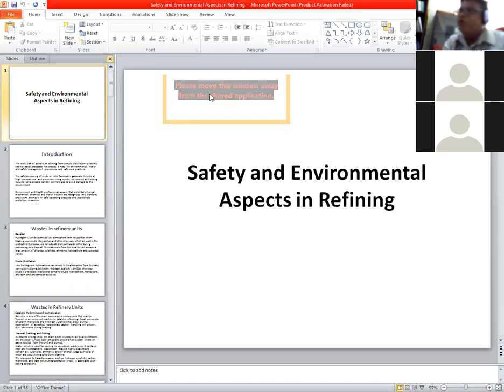This is very common. To avoid vapor cloud explosion, this is an explosion, and there might be fire also, because fire can be created from explosion. So we should not allow leakage in the pipeline or at the joints, right? Joints in any elbows or any flanges should be very tight and should not allow the leakage of gases.